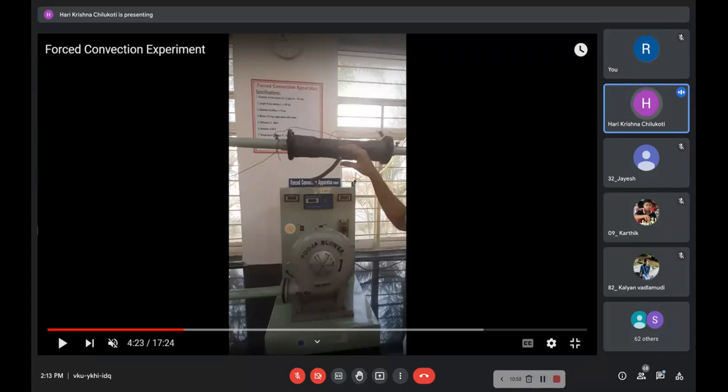Again, similar to the previous experiment, after switching on the power, we need to take the 8 thermocouple readings every 10 minutes. And when the consecutive sets of readings do not change, then we can say that the system has reached the steady state. That means the heat input given is equal to the heat carried away by the forced convection plus the nominal heat losses by heat transfer to the surroundings as well as by conduction through the other portion of the tube.